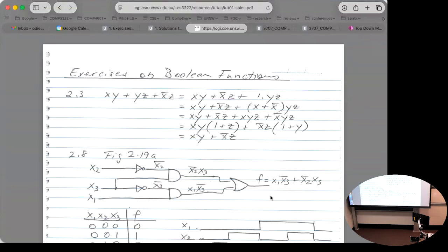I have a question about changing to using the NOR gates only, but it's for next week's exercises. Can I also ask? Well, we talked about it in lectures, so yeah, that's fair enough. In the fourth one, in that exercise, for one of the wires, it's a split between two wires, and when we add the bubbles to an AND gate, it only had one bubble, so we have to add one more. Mm-hmm. But would that extra bubble we add be before the split or after the split?